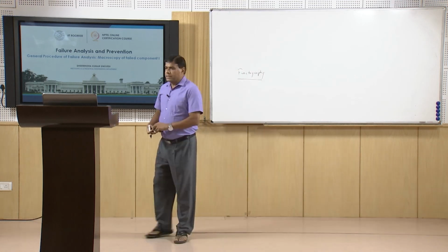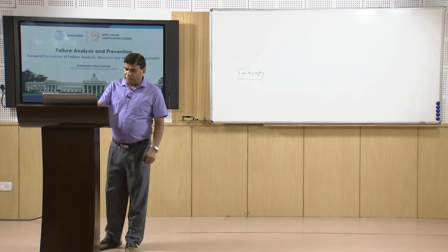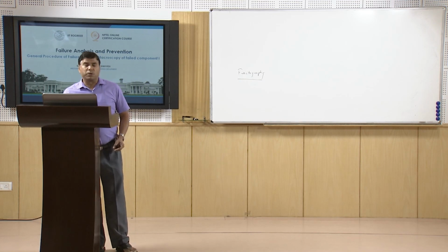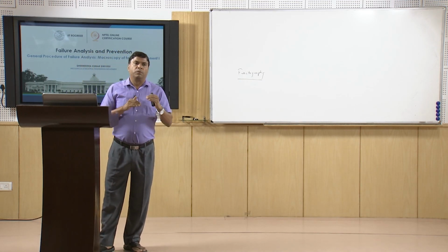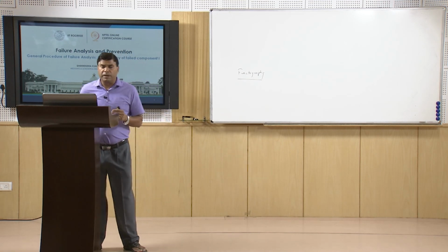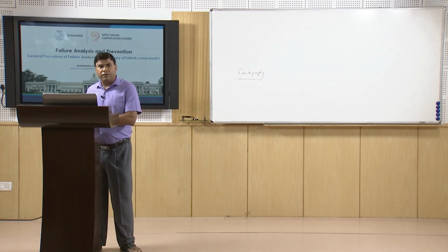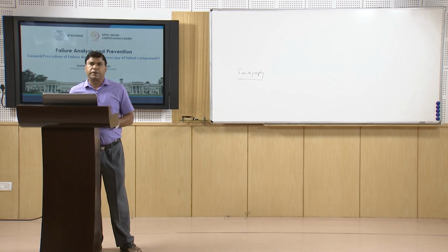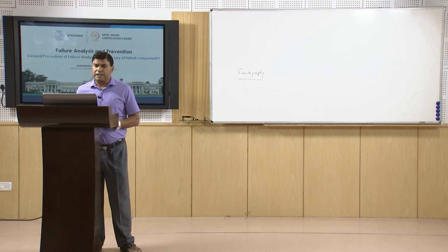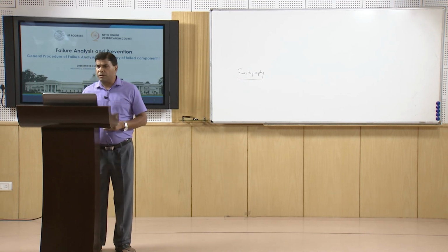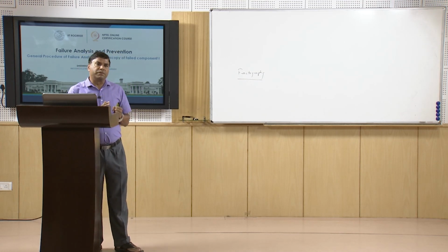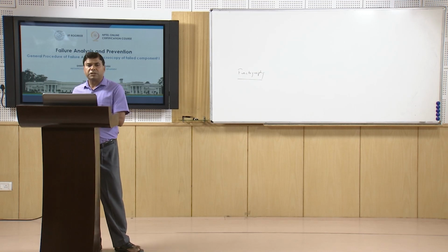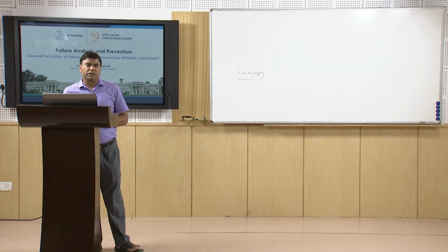Now, what is fractography carried out for? As I have said, it helps to identify the loading conditions and the environmental conditions which have led to the failure of the component. In line with that, the basic purpose of fractography is that it helps to determine the root cause of the failure among the fundamental sources of the failure.